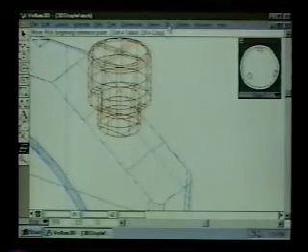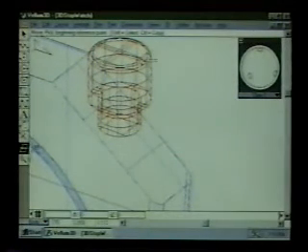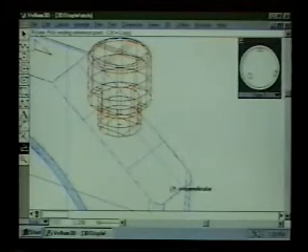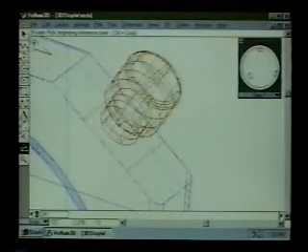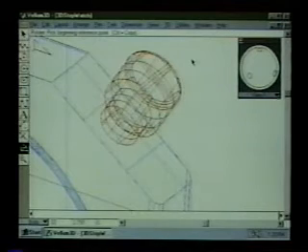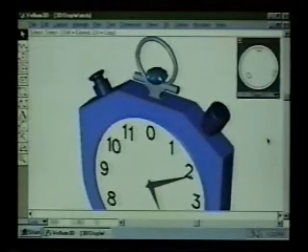Then we can change the plane back to front so that we can rotate this thing properly. Get the z-axis pointing in the direction of the axis of rotation. Use the rotate tool. Pick the center as the center point of the rotation. The end point out here, or the quadrant point, is the beginning point of the rotation, and this point along this line is the ending point of the rotation, and that rotates it into position. So either one of these methods works just fine and gets your part located in space using the drafting assistant. And once we're done, we wind up with the shaded watch.